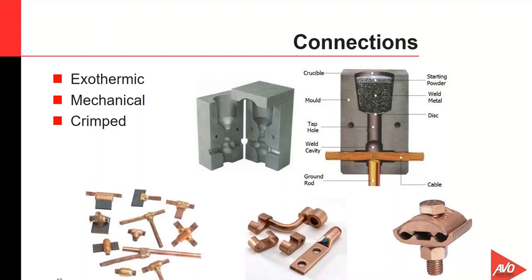The way this process works is that it employs molten metal to join those conductors, because ultimately what we want to achieve is the exact same replication of the conductor inside that system. Exothermic allows that with the best capacity. The process uses a thermite composition to heat the metal, using an aluminum powder and a metal oxide. It requires no external source or heat unit.